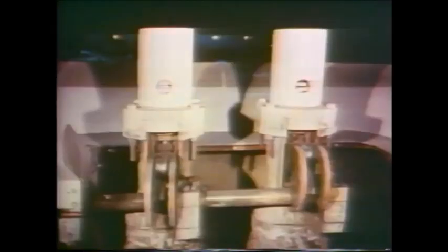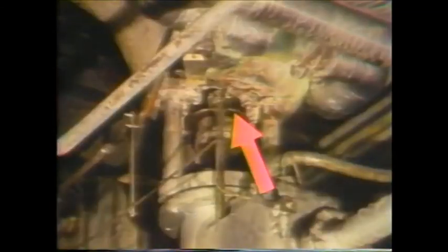This means that all four valves, the stop valves, the control valves, the reheat stop valves, and the intercept valves quickly close, cutting off all steam to the unit. A trip protects the turbine from danger by immediately shutting it down. Well, we've now covered turbine construction and how the construction allows the turbine to produce power.